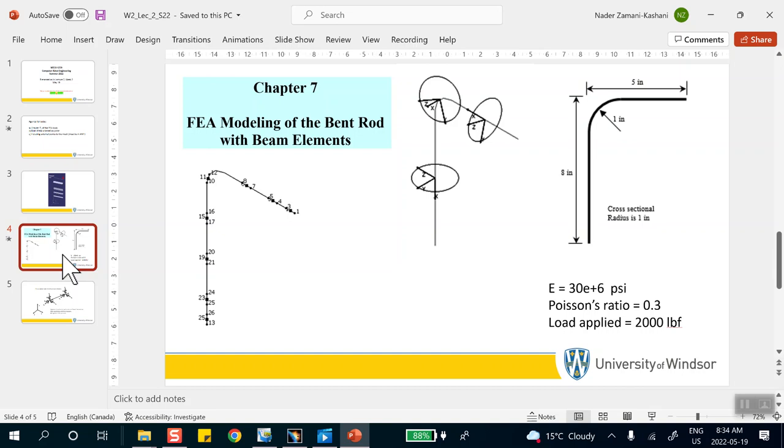All right, let's move on. The way it works, you draw a line in space, just like you did in stress analysis. And you tell the software what the cross-section is. If it's a circle, no problem, very easy. And the line is broken into beam elements. Beam elements are just little pieces on top of that line, okay? Element 1, element 2, element 3, going along the beam. So you can see on the left side, for example, I may have 10 elements, 20 elements. The middle number gives you the element number, the number on the side gives you the node number. So this is what we do.